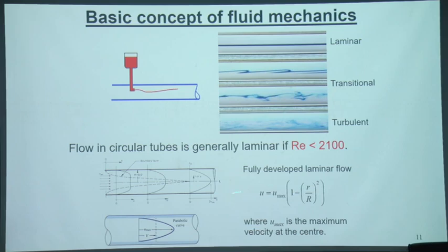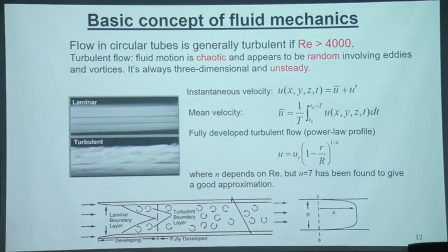If you read any basic fluid mechanics textbook, you will find this solution, where the theory allows you to calculate the entrance length required for flow to become fully developed into a parabolic velocity profile. When we have a parabolic velocity profile, the maximum velocity is at the center, and the maximum velocity is 2 times the average velocity across the cross-section.